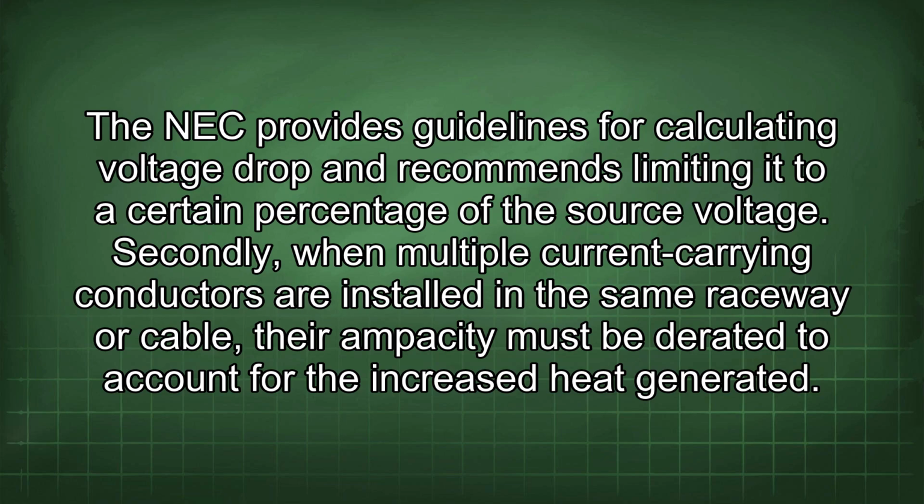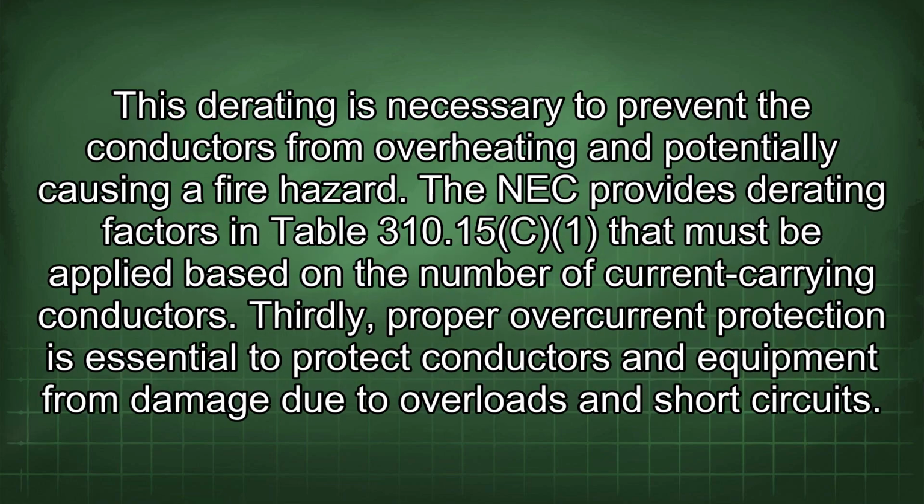The NEC provides guidelines for calculating voltage drop and recommends limiting it to a certain percentage of the source voltage. Secondly, when multiple current-carrying conductors are installed in the same raceway or cable, their ampacity must be derated to account for the increased heat generated. This derating is necessary to prevent the conductors from overheating and potentially causing a fire hazard. The NEC provides derating factors in Table 310.15 that must be applied based on the number of current-carrying conductors.